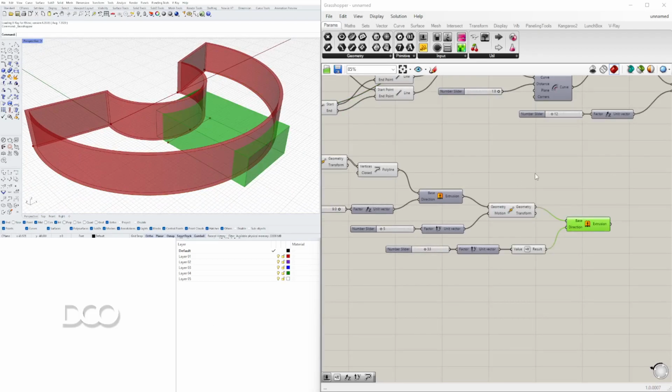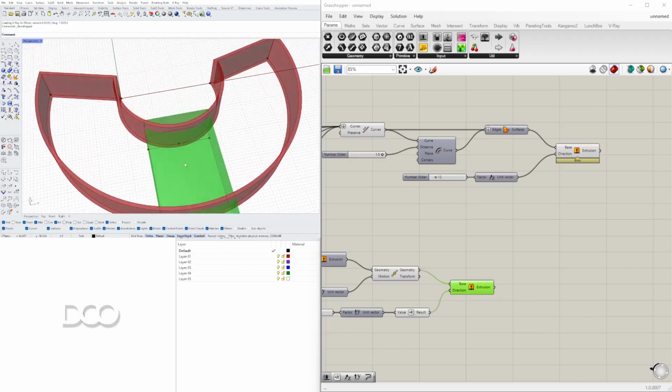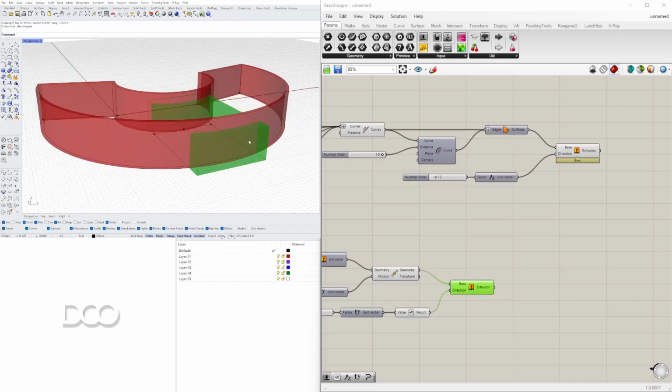We'll have this extrusion that intersects this, and we'll subtract it. What this will do is create the opening for the courtyard and possibly kind of the front entry. Now this is going to be a basic form, so don't expect to see a lot of detail. Some of those things can be taken care of inside of the modeling.